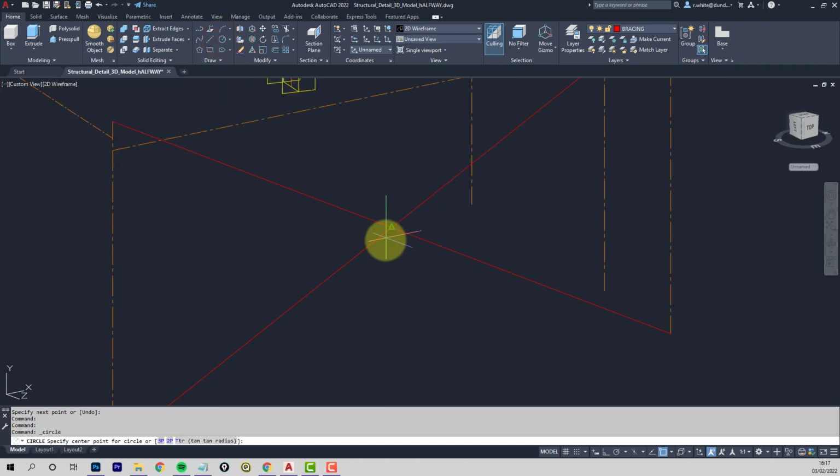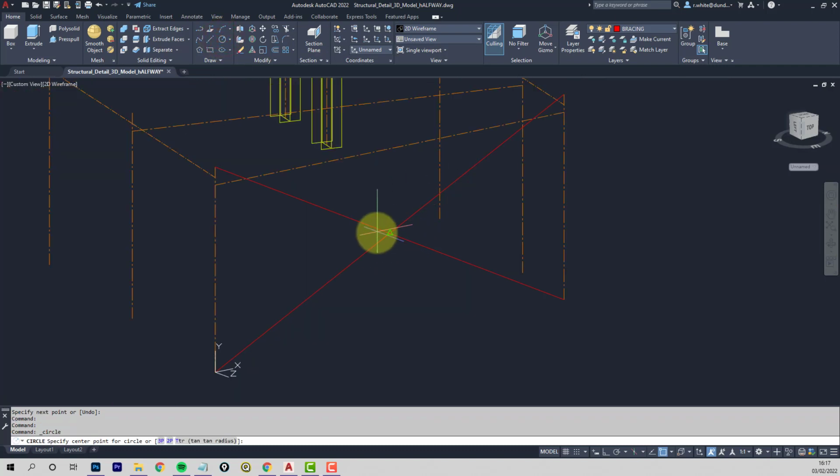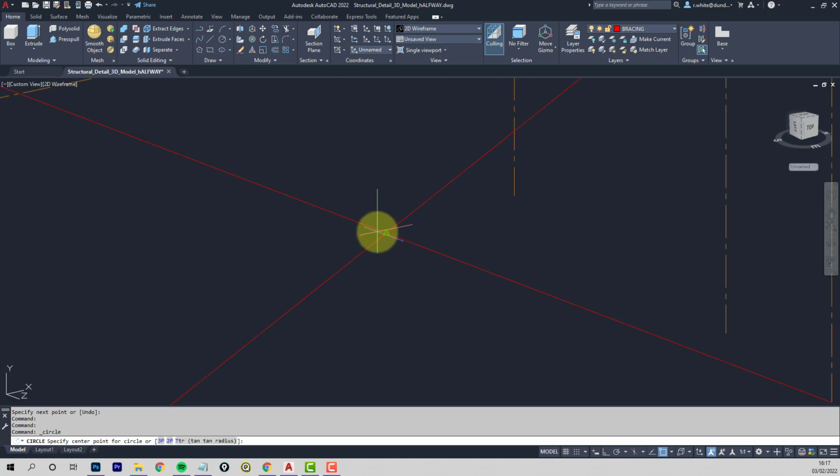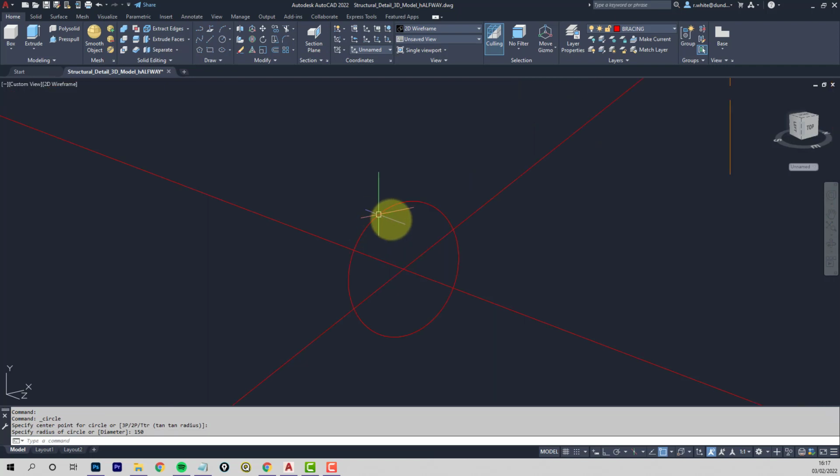Okay, this is very accurate. These lines do hit each other and they intersect, so we'll intersect there, and we'll put a radius of 150. I want this to look solid, so I'm going to give that thickness of 10 millimeters. That's thick, that's strong. So we offset by 10, enter, and take this out the way.